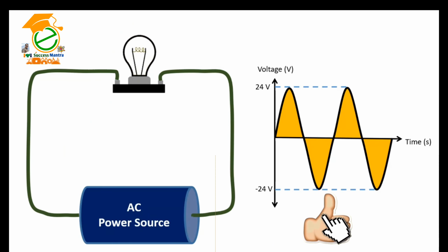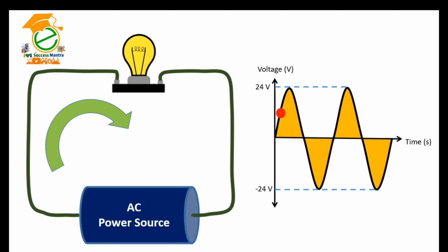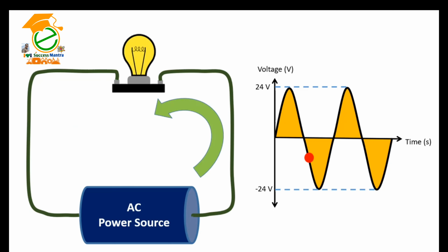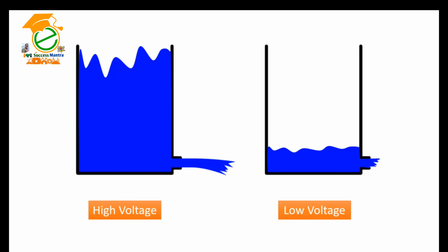With alternating current, the direction electricity flows throughout the circuit is constantly reversing. You may even say that it is alternating direction. The rate of reversal is measured in hertz, which is the number of reversals per second. So, when they say that the US power supply is 60 Hz, what they mean is that it is reversing 120 times per second.